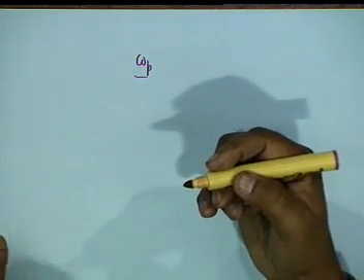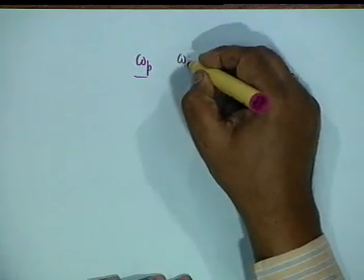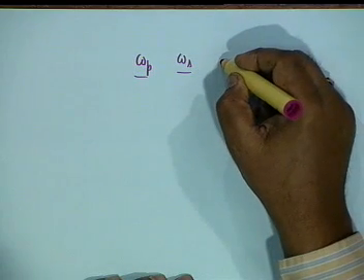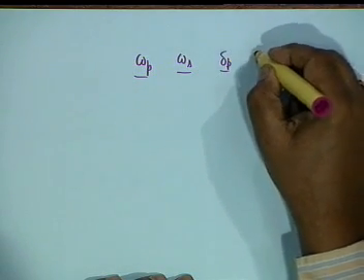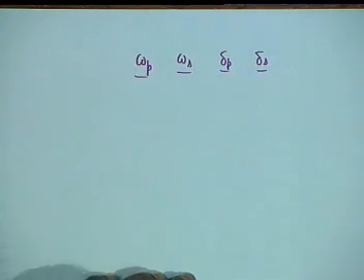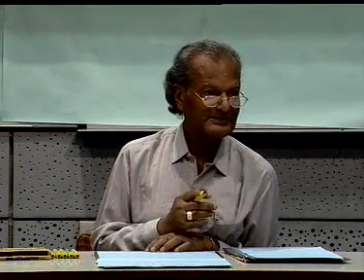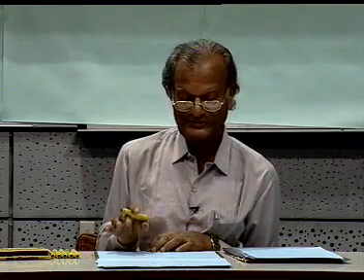For example, even a simple band pass filter has omega p1 and omega p2, then omega s, then delta p and delta s. Now these delta p's may be different in different pass bands. Then you choose the minimum tolerance. If you can tolerate 3 dB, obviously if you give a 1 dB tolerance, your boss will be happy. To keep life simple, you make them uniform.